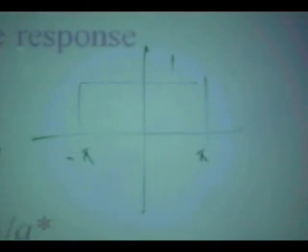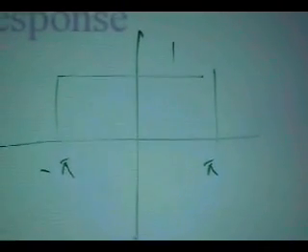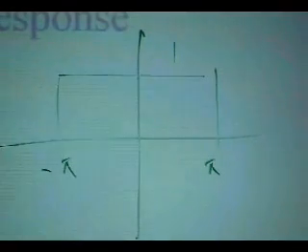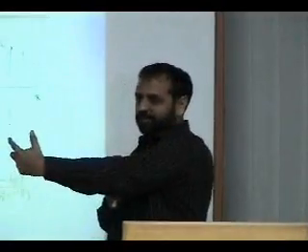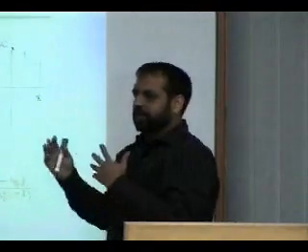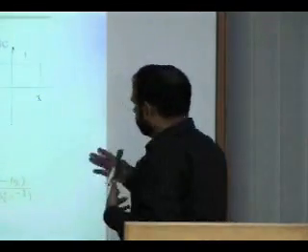So a question is, why do you need an all pass filter? Because it's not going to alter any frequency content, but all pass filters can change the phase. So usually you can use an all pass filter to compensate for phase distortion. You say, okay, this IIR filter is causing this phase distortion; if I place an all pass filter, it will help me cater for the phase distortion. You use it for that.